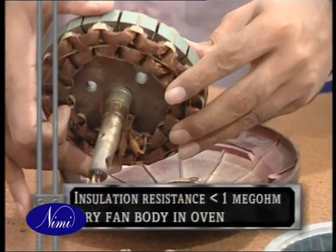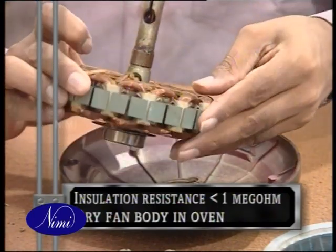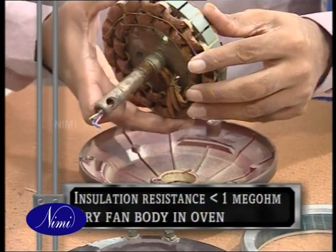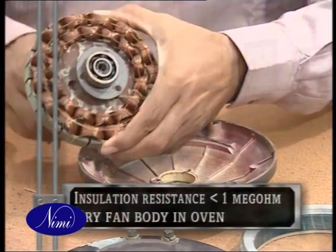On inspection, if any trace of moisture is found on the motor, the fan needs to be tested for its insulation. If the insulation resistance is less than 1 megohm, then the fan body needs to be dried by using a 500-watt bulb or in an oven.